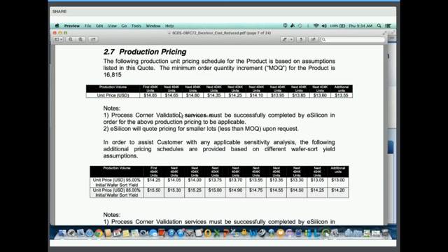Anybody who's done a quote manually for custom IC knows that one of the things people live in fear of is, do I have the right options? Have I picked a set of options that don't necessarily play together well at the foundry? It's kind of rough finding that out when you're in the mask shop, or worse, on the processing floor. So our interface basically limits you to only pick the options that make sense for that set of choices.